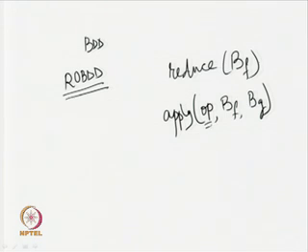One main constraint on this apply algorithm is that Bf and Bg should have compatible variable ordering, and whatever resultant BDD we are getting will also have the similar ordering as Bf and Bg, but the output BDD may not be a reduced one. So, after that we can apply the reduce algorithm to get the ROBDD.